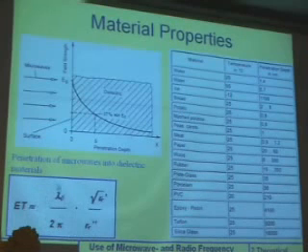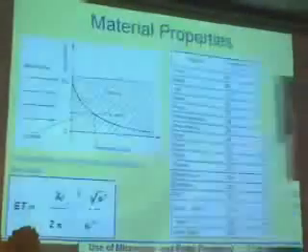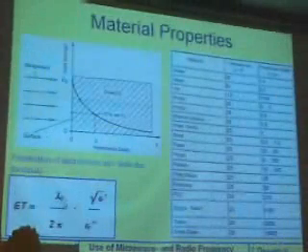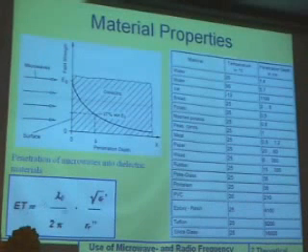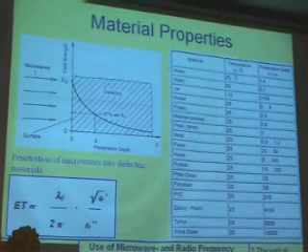And now you can see some interesting things. The lower the frequency and the higher the wavelength, the higher the penetration depth. And the higher epsilon R, the lower the penetration depth. And you can see this here. We have here the calculated penetration depth of different materials, and I will start perhaps with water. You see, water at the temperature of 25 degrees centigrade has a very high epsilon R, and therefore the penetration depth in water is only 1.4 centimeters.